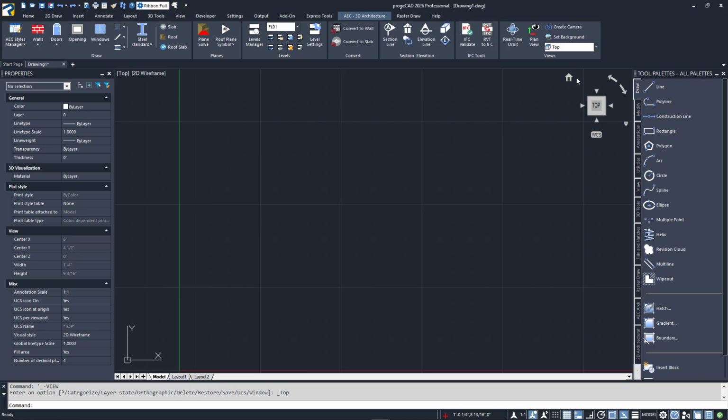The icon at the bottom that reads WCS allows quick access to any custom user coordinate systems you may have, or the orthographic projections as we saw in the viewport tools. The two curved arrows will rotate your view 90 degrees from the current Z-axis.